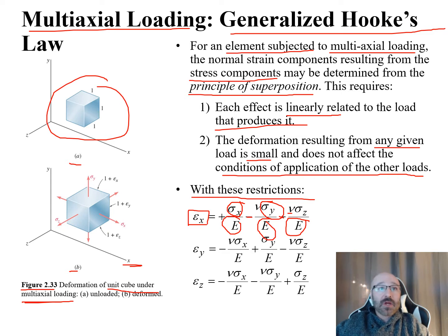We can go back over here. You can see here is our stress in y, stress in x, and stress in z, all corresponding to the coordinate system that we have shown here. So this is another really great reason why you want to have your coordinate system drawn out, especially when you're talking about 3 dimensions, but even in 1D and 2D, having these labeled, knowing which axis is which, and knowing what's positive and what's negative according to your chosen axes.